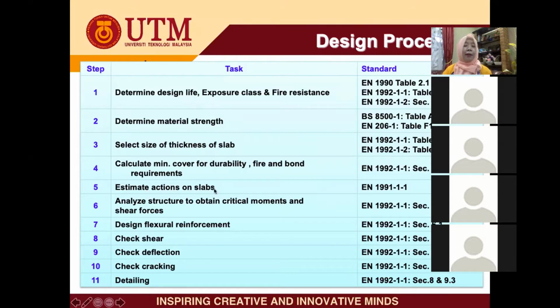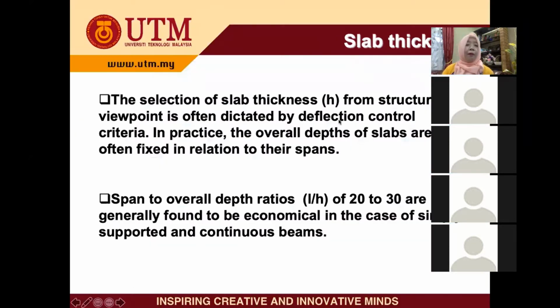In fact, we have already covered this one when we did the beam design. Analyze the structure to obtain critical moments and shear force. Also here we will use a method similar to the beam. Design flexural reinforcement. Yeah? Check for shear, deflection, cracking, and detailing. Okay.